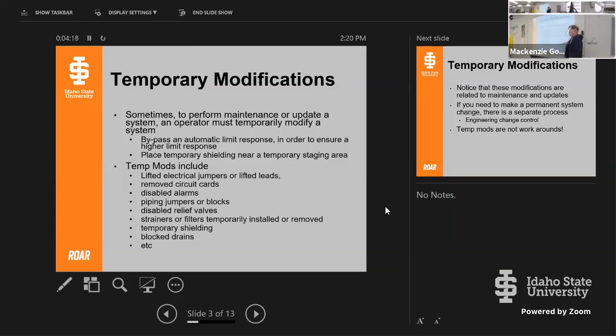So each one of those steps is going to give you time to ensure the reactor never gets close to that safety limit, right? But sometimes, to make sure each one of those limits receives a signal, activates like it should, gives you the correct mechanical interlocks and alarms, you have to bypass this lowest level one and then introduce a test signal so you can test that next higher one, and so on and so forth, all the way up your alarm interlock bus.